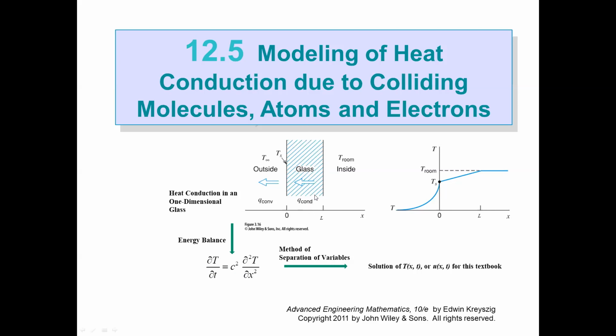This system, heat transfer inside the glass or a piece of metal, can be analyzed by energy balance. If we take an energy balance, we shall be able to obtain a partial differential equation like this. Notice this is a second order partial differential equation because the highest derivative in the equation is second order.